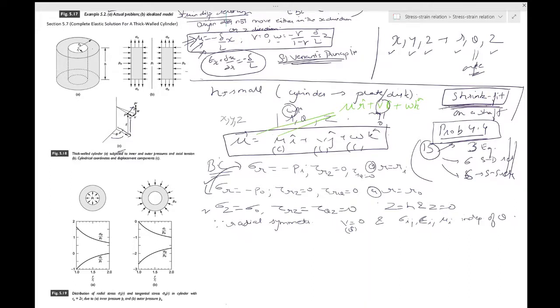The whole point is that whatever stress you get at this value along this whole circle, you will get the same stress or strain or displacement. So it will not depend on what theta you are at, as long as you are at the same r and same z. Okay, that's the first part about this, and this is what you are looking for.